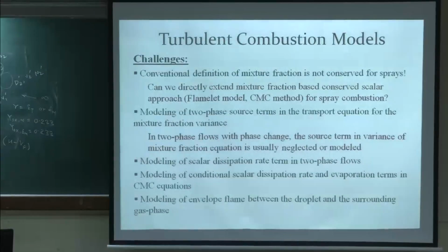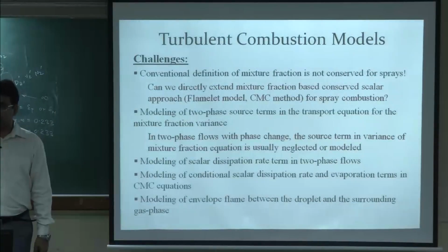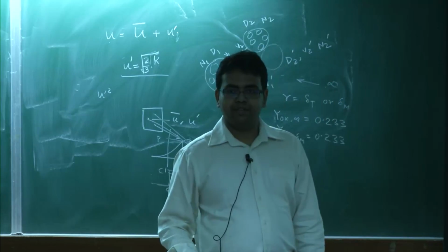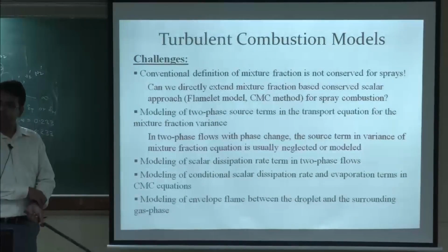Now the question is whether we can apply the conventional models in our case. Okay. That is the biggest question for spray combustion. So can we apply the conventional flamelet model, conditional moment closure method, all these things in spray combustion. Okay. Basically, can we use the presumed PDF approach directly, because now the mixture fraction has a source term due to the evaporation of the fuel.